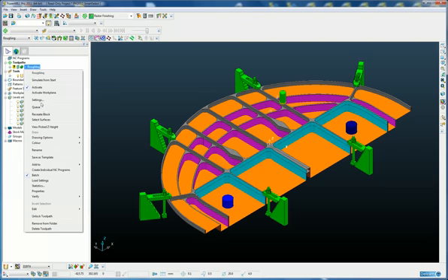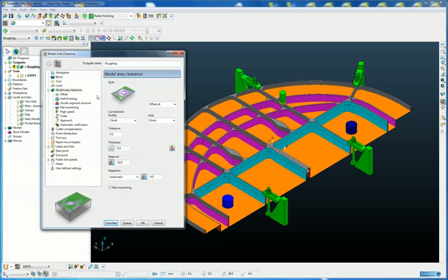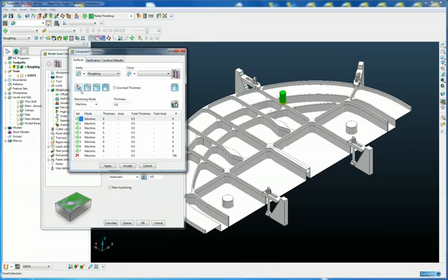I'm going to go into this toolpath, into the settings, and we're going to set up the component thickness using Smart Selection. So we're going to go into the component thickness form, and there we can see a new button called Smart Selection. So we select our component set as previous, set whether we want to collision, ignore or machine. In this case I'm going to set it to collision, and I'm going to add an extra thickness of 5 mm. The reason for this is I want to collision check the clamps and I want the tool to stay well away from those clamps.